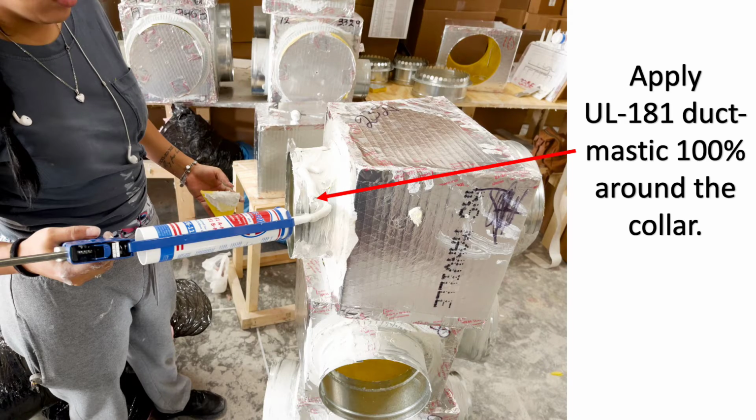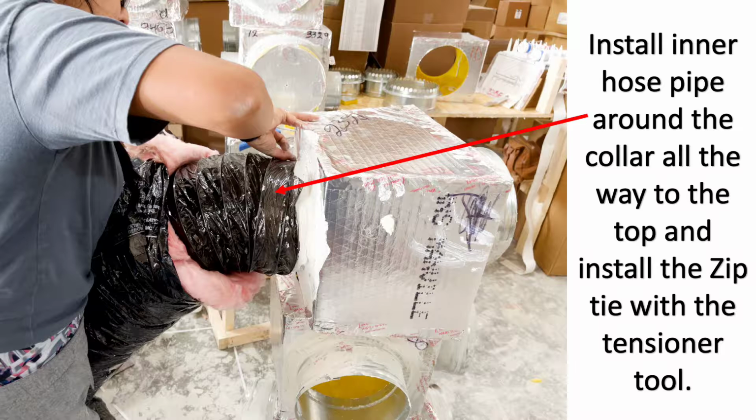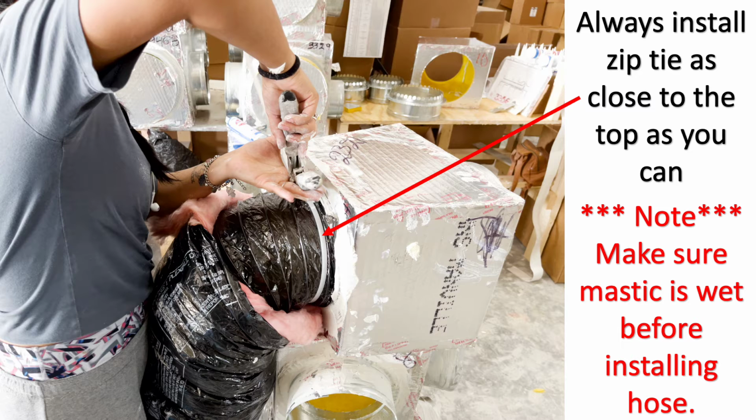Apply UL 181 duct mastic 100% around the collar. Next, smooth the mastic with an applicator to control coverage. Install the inner hose pipe around the collar all the way to the top and install the zip tie with a tensioner tool. Always install the zip tie as close to the top as you can. Note, make sure mastic is wet before installing the hose.